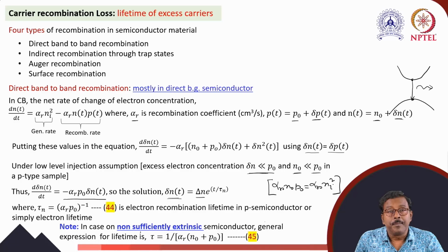In case these assumptions are not valid, that means n0 much less than p0, that is, if the semiconductor is not sufficiently extrinsic, in that case the lifetime expression will contain both the terms n0 and p0.